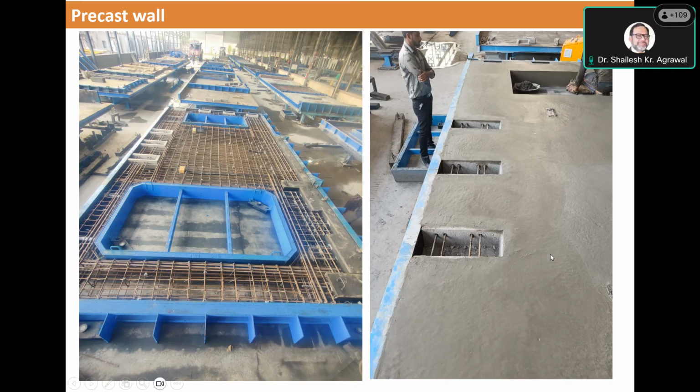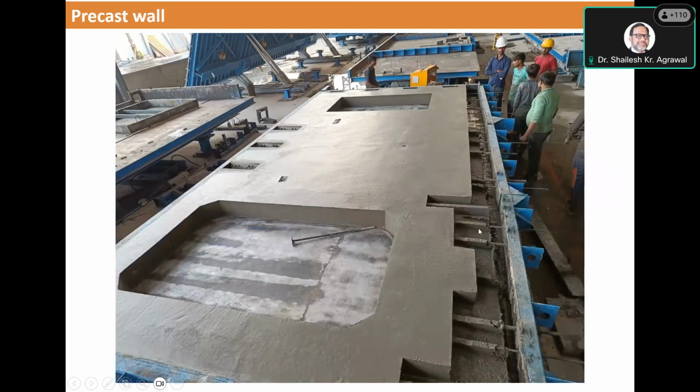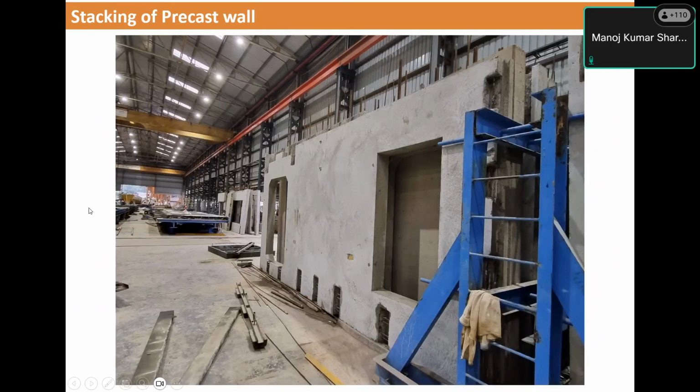Okay, likely changes in future. The next question: can we replace steel by FRP? No, FRP still is not recommended for structural use application. In the first place, FRP is very good in tension, but not good in shear or compression.